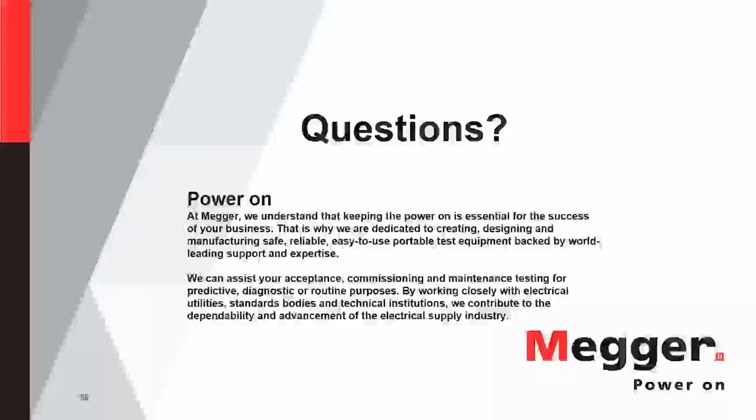So if you do use an analog rotary transducer, what I say is always measure it and put it at 50%. That way, if it rotates one way or the other, it doesn't matter because you're not really going to be spinning around 180 degrees. So you won't have a problem measuring with that. The reason I like a digital is because I can just hook it up and it can spin around 10 times and it just keeps kicking out pulses, and it's not a problem.